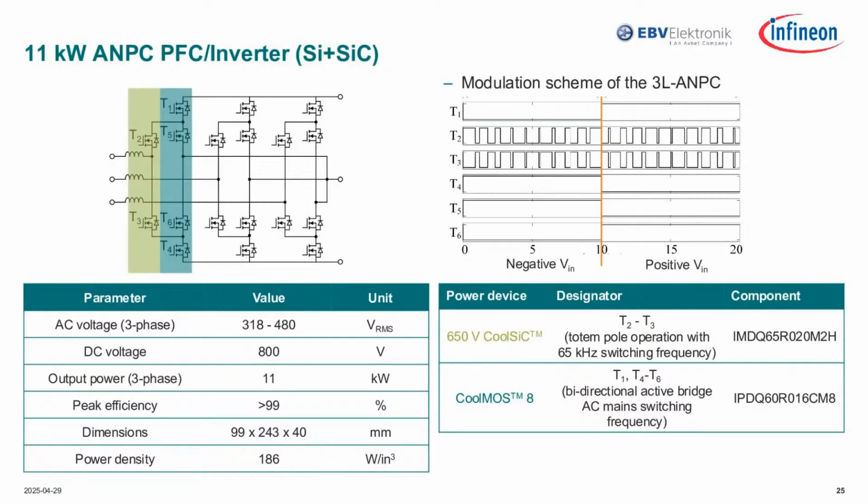Considering driving losses, switching losses, and the balance of design effort, silicon carbide is more appropriate in this application. Also, one advantage of silicon carbide in the PFC stage is the higher temperature, meaning that you can use a relatively low RDS on, let the TJ go up a little bit, and then provide better system cost balance and performance.